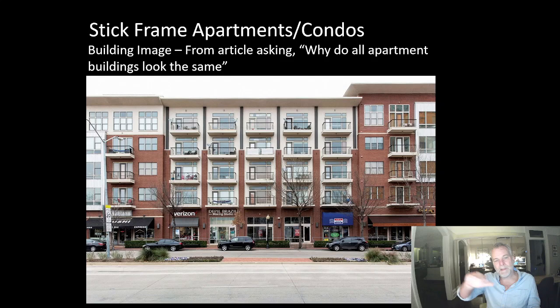that all the buildings, the balconies are completely wrapped. And you might wonder why. It's not a thermal separation, and yet they've completely wrapped the building with the balcony. And the reason is, as I mentioned before, that wood in an exterior environment, even if it's pressure treated, has a 15-20 year life. And we're designing buildings, if we're doing it right, we want a building to have a 100 to 200 year life. And so we've got to protect those elements.